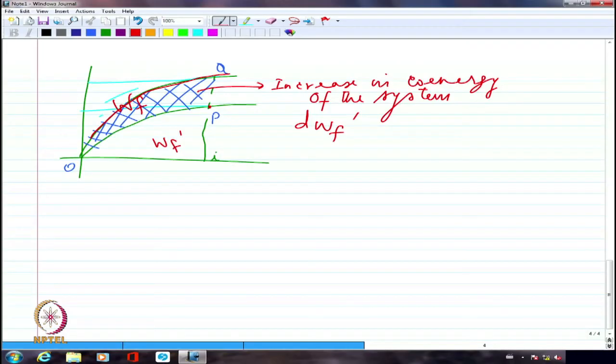We don't know whether the quantity is the same in the previous case and this case. In the previous case, we considered there was no movement, and only one particular magnetization characteristic. Whereas in this case, we have considered two magnetization characteristics, one at length x1 and the other at air gap length x2. We considered x2 is smaller, which is why we drew that curve above the previous curve, assuming that the reluctance is smaller, because of which the flux should hopefully be larger. I hope your question is somewhat clarified, if not completely.